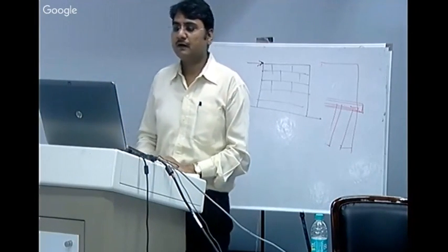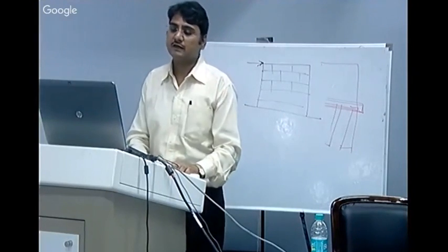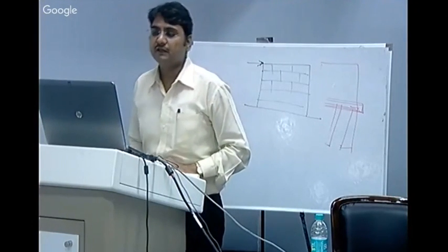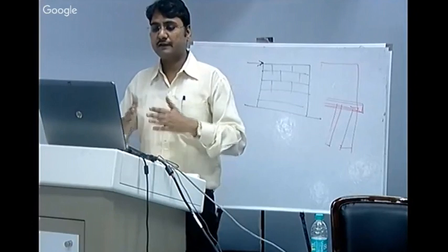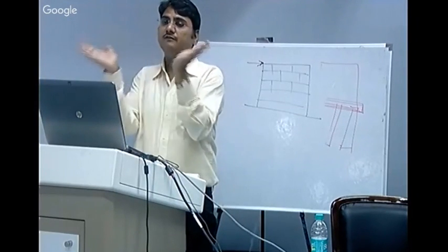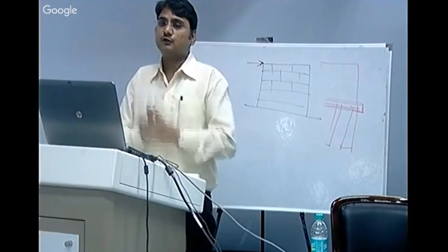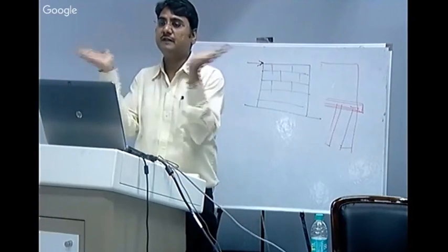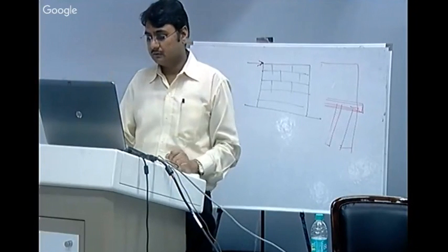This is how the mud wall collapses if you are not having through stones in between the walls, because when the earthquake force is there, the splitting of the wall will happen. The two portions of the wall will split from the middle portion, and it will collapse.